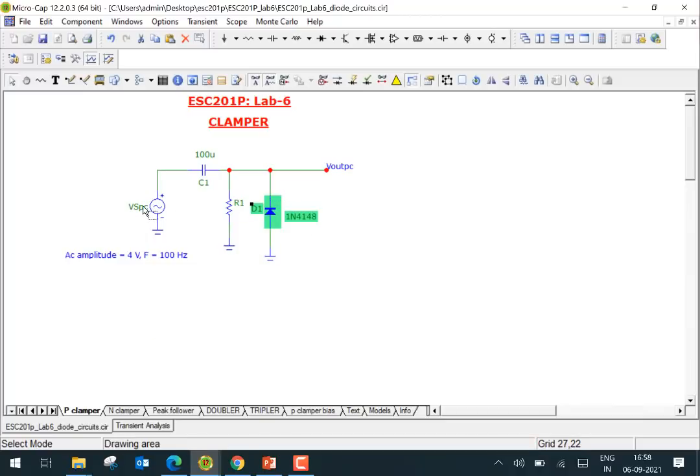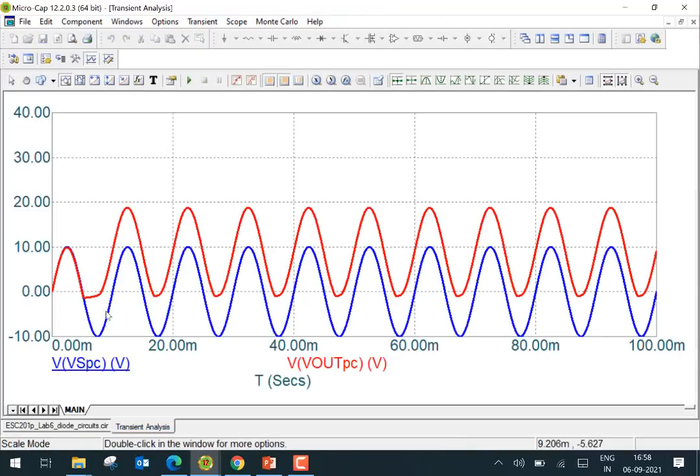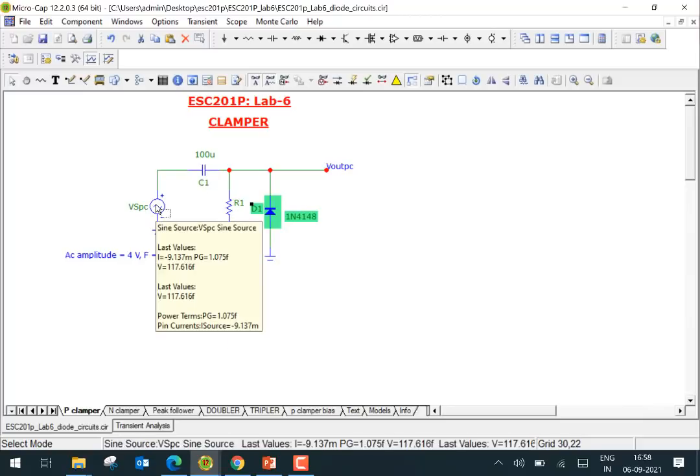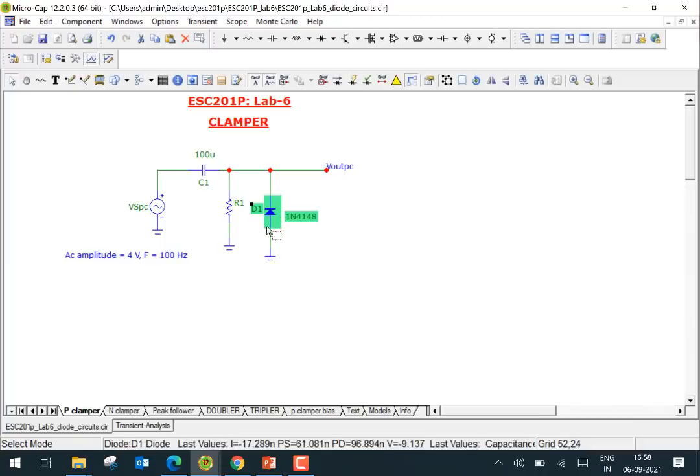But in the reverse case, the moment it goes negative, the capacitor is like transparent. You can monitor the voltage across the capacitor. The fact that the output follows the input during the initial part means the drop across the capacitor is negligible. It's not able to charge. That's where the role of the time constants and all that you will explore. In the reverse bias, the moment you go reverse bias, the diode offers a low resistance path and the capacitor is able to charge in the negative direction, except for the diode drop. So the capacitor acquires a charge or a voltage here.